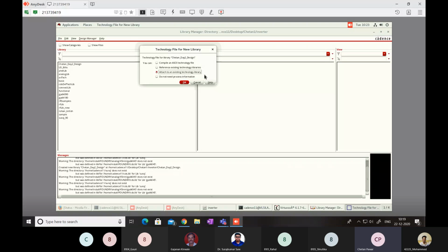For that purpose, you need to ask the fabrication unit to give the PDK of your fab unit so that we can construct a chip for that particular design, by using your foundry. Similarly, we need to connect our library to one of these, GPDK 90 or GPDK 180.